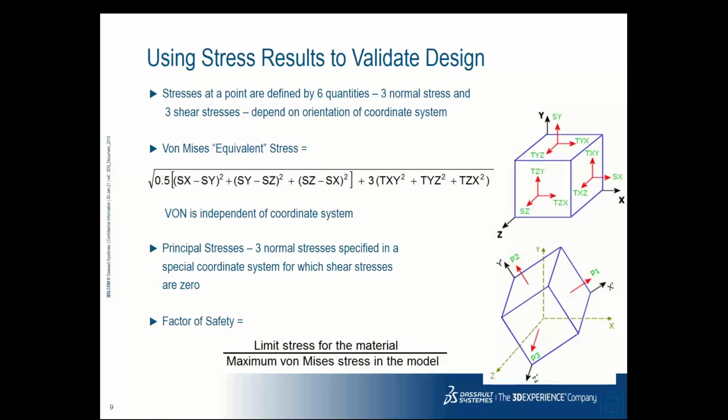Okay, so whenever we consider a coordinate system or any kind of element in space, and we apply loading, we basically consider the von Mises failure criteria for performing the FE analysis, that is the shear strain energy criteria. According to this von Mises criteria, if we apply a loading on certain components, it has three normal stresses and three shear stresses. So this is the formula for von Mises. If you want, you can write it down for your reference.